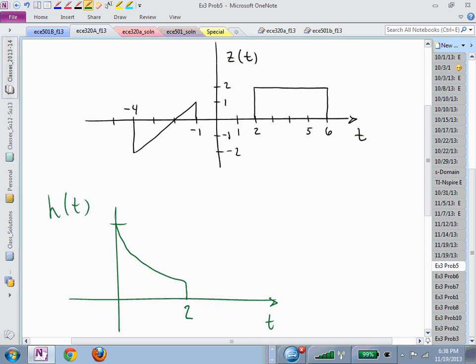Can I make a graph of that? Well, when you're solving these convolution problems, if you have finite duration lengths for your excitation x or your two waveforms, x1 and x2, then the start time is the sum of the leftmost endpoints. In this case, it was -4 plus 0. And when is its end time? The sum of the rightmost values, 6 and 8.